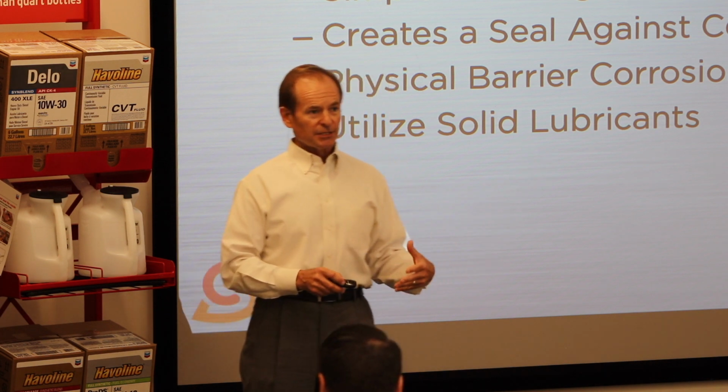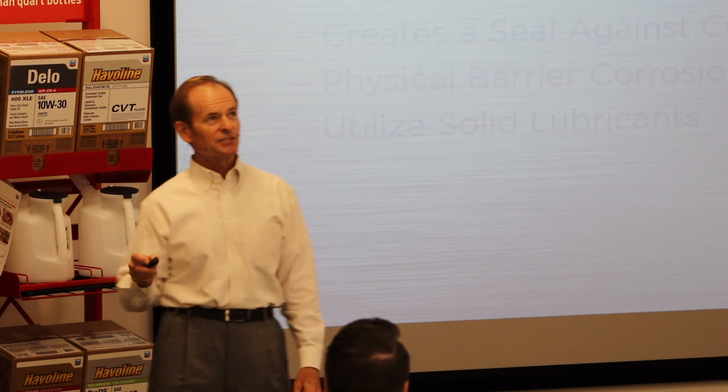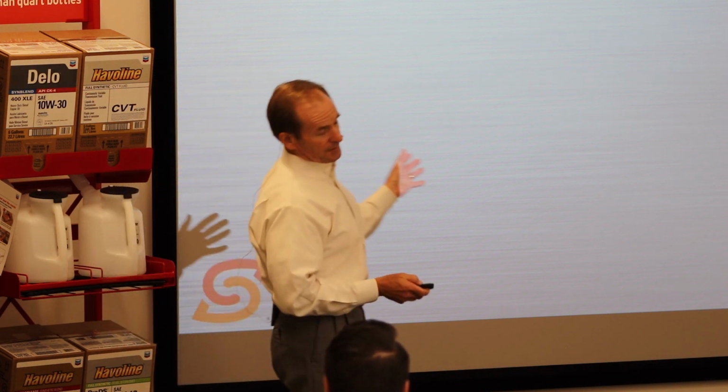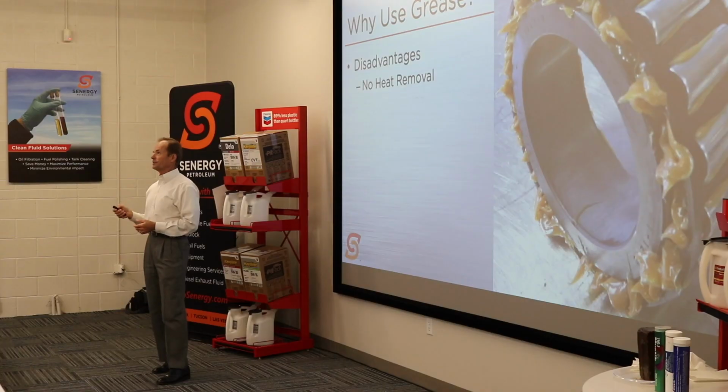Of course, anytime you've got a list of advantages, you have disadvantages, right? So let's talk about some of the disadvantages of grease. One, and a big one, is you don't get any heat removal. When you've got something that's oil lubricated and you have some flow of oil, the oil also assists in carrying away heat. That doesn't really happen with grease. In fact, grease, depending on how much is built up, can act like an insulator and keep heat in place. So that's a disadvantage you have to consider.